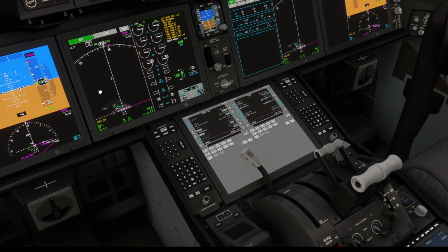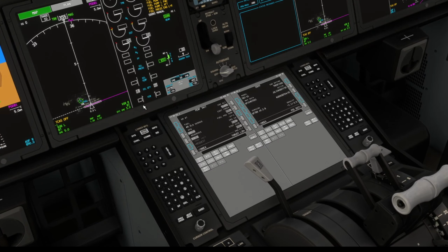Okay, so I'm back with the fuel figures, and the flight plan indicated to us that we need block off fuel of 46,000 pounds, and choosing 49.2 today, just round it up a little bit. But for the reserves indicated at 11,936, we would round that one up to 12,000, 12.0, like that.